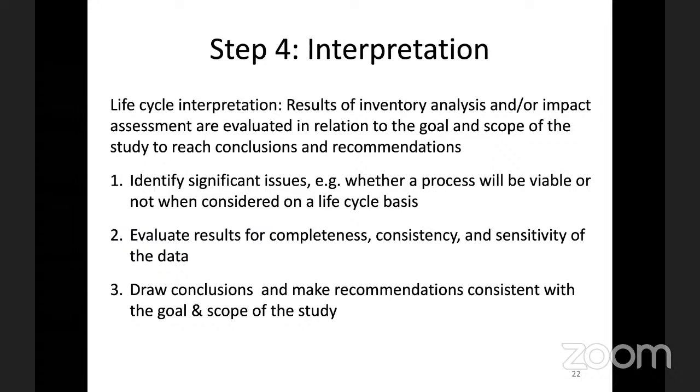And step 4 is pretty straightforward, where you have life cycle interpretation, and results of inventory analysis and impact assessment are evaluated in relation to the goal and scope of the study to reach conclusions and recommendations. And with this, you identify significant issues, whether a process will be viable or not when considered on a life cycle basis. You evaluate results for completeness, consistency, and sensitivity of the data, and then you draw conclusions based on that.